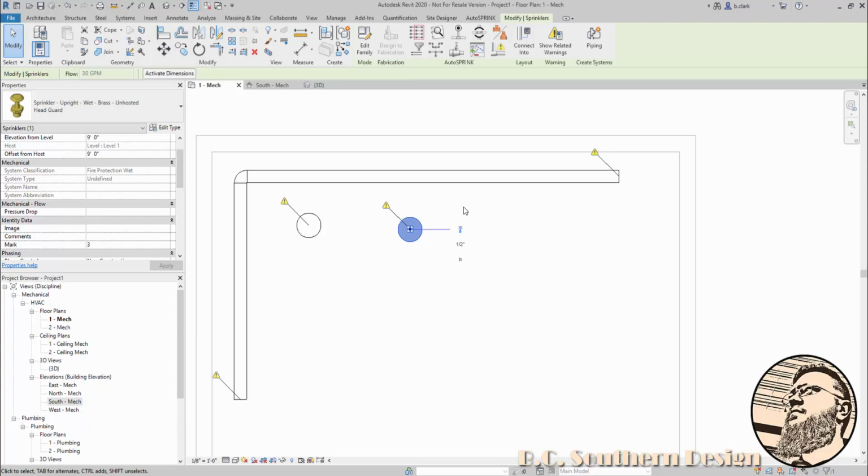You have to actually force them on. This is another one of those, in my opinion, minor annoyances with this tool, because I guess Revit sees them as two separate objects versus just paying attention to the host family and going off of that. It sees them as individual families being brought in independently, so it can't give you the temporary dimension.